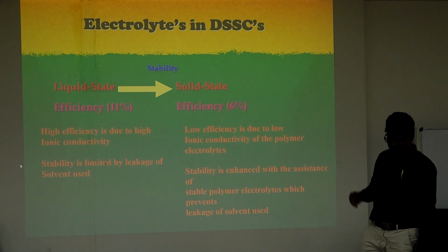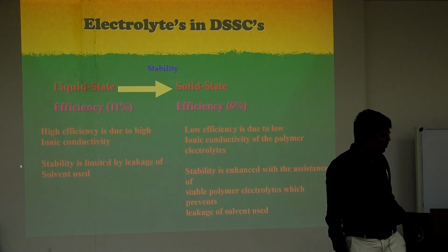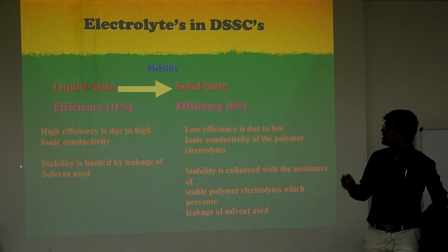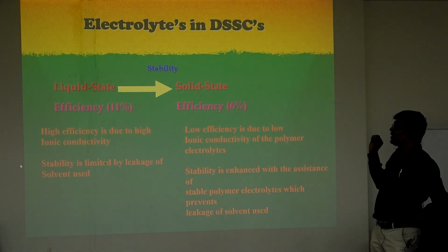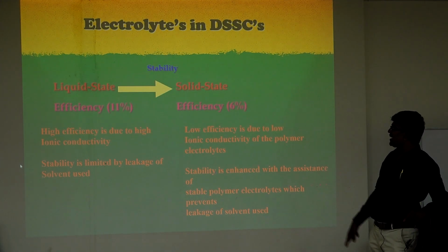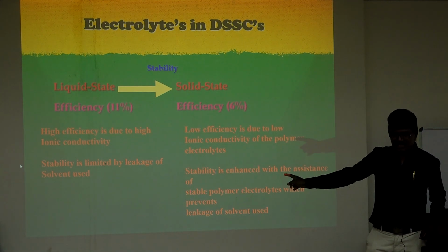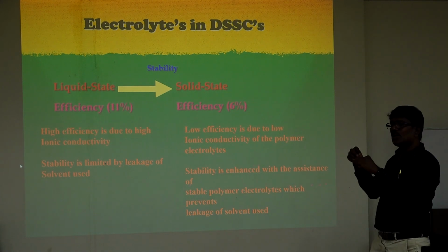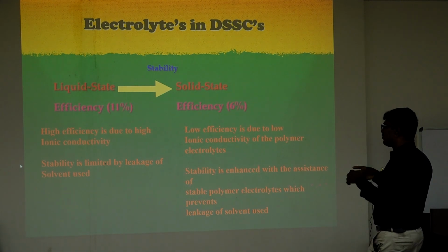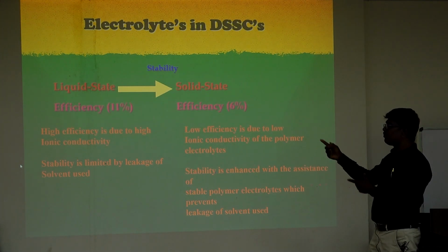Now come to your dye-sensitized solar cell, third point: the electrolyte. So the electrolyte is very important here, iodine iodide. With low cost, we can prepare iodine iodide and get a maximum of 11% in laboratory conditions actually. The drawback is that the liquid electrolyte can leak. When you put the solar cell, it can leak out from the cell and the cell may break actually. We will show the slides maybe Thursday afternoon on how to make this one.